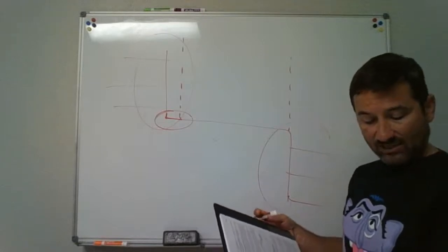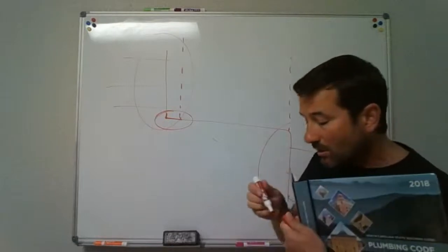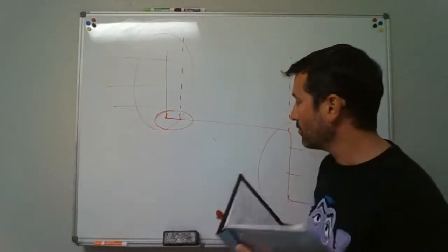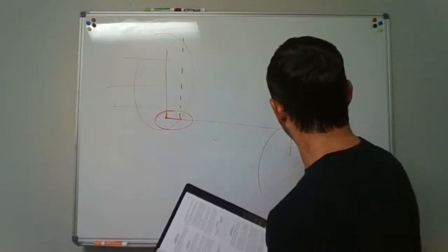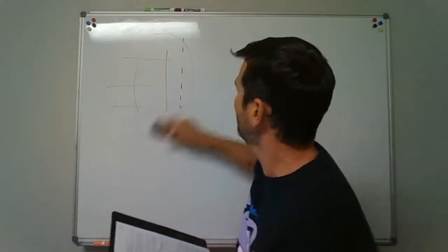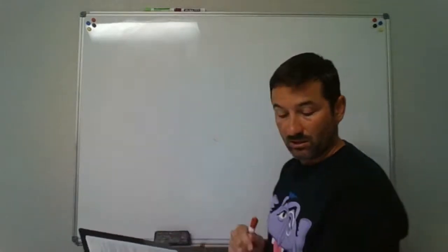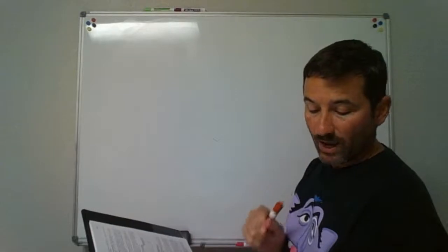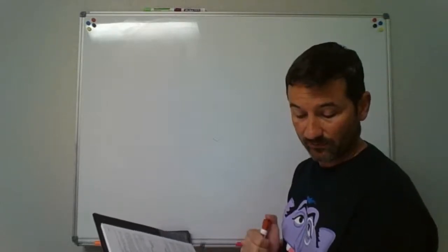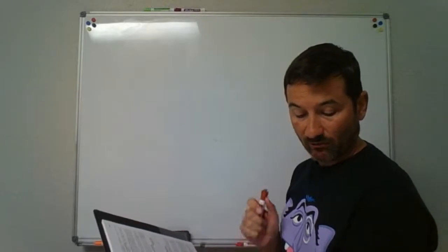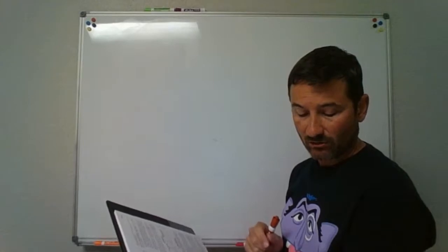Relief vent stacks of more than 10 branch intervals. All right, so we've got at least a 10-story building here with plumbing fixtures on each floor level. And it says soil and waste stacks in buildings having more than 10 branch intervals shall be provided with a relief vent at each 10th interval installed.